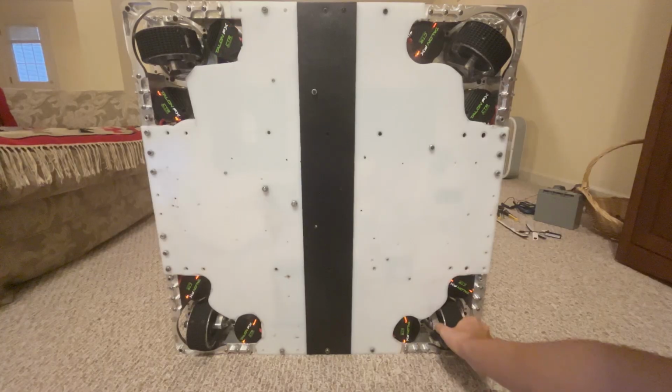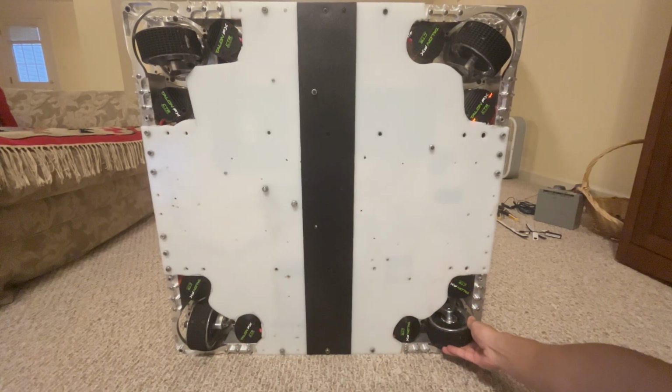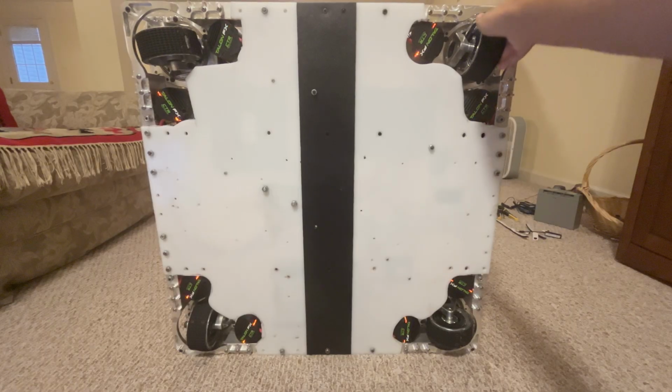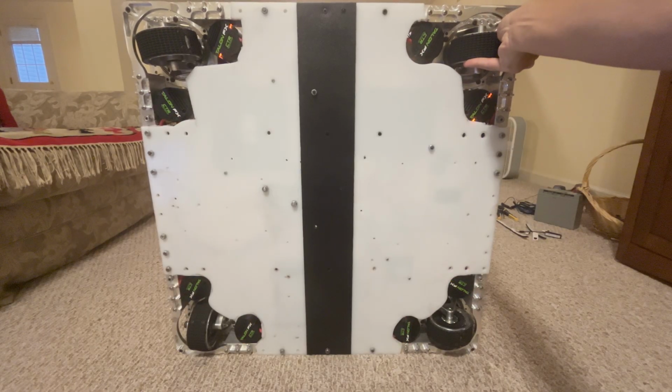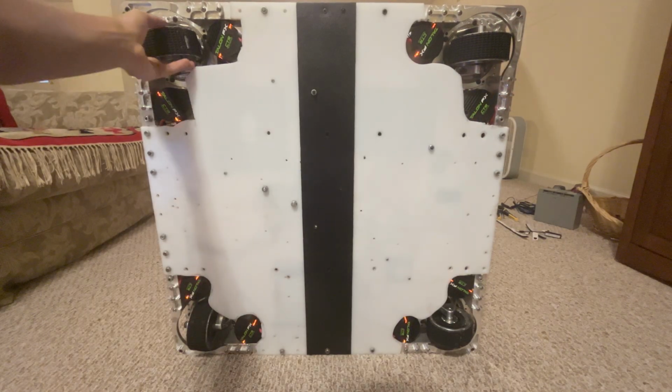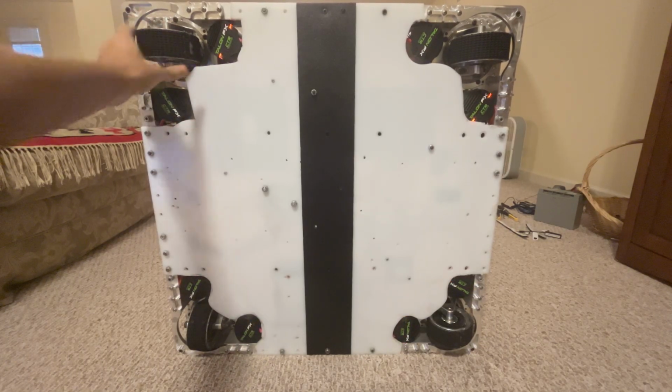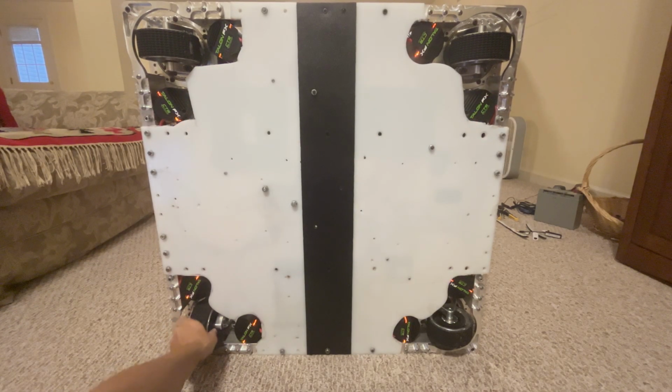Okay, now adjust all of the wheels to be facing forward, and take notes on all of the encoder readings. These will be our wheel offsets, because at these readings, we know the wheel is actually at the 0 heading. Also, to tell if the wheel is facing forward, look at the bevel gears and make sure all of them are facing right. If the bevel gears are facing left, the wheel is actually pointing straight backward instead of straight forward.